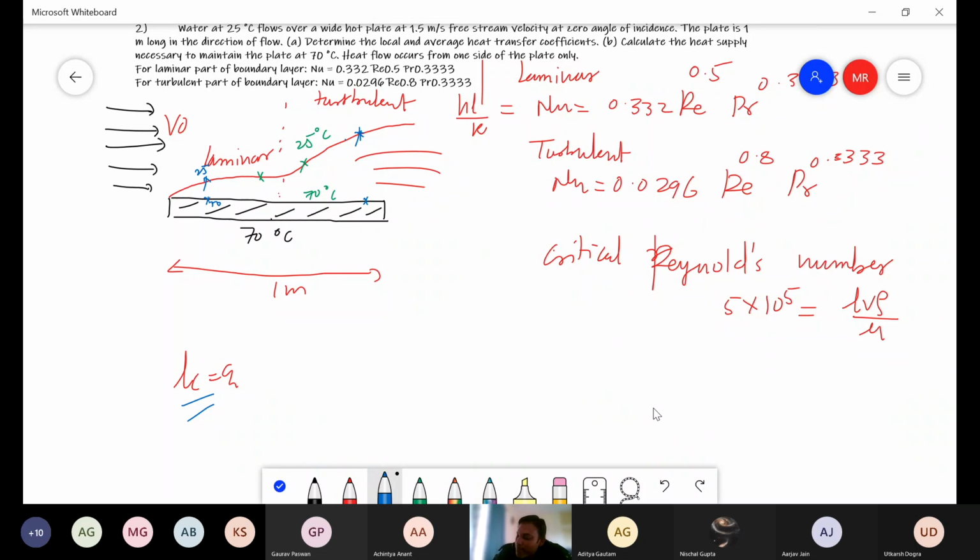Did you see the problem? I'm trying to give a perspective in more detail here. I am saying the temperature here will be 25. Here at the surface it is going to be 70. And I need to calculate the Reynolds number for the fluid which is flowing in between. So which density and which viscosity should I take, because density and viscosity will be dependent on temperature? So which one should I take?